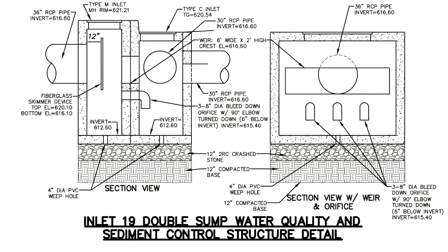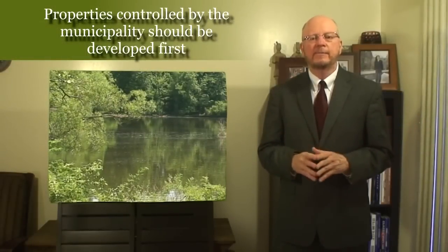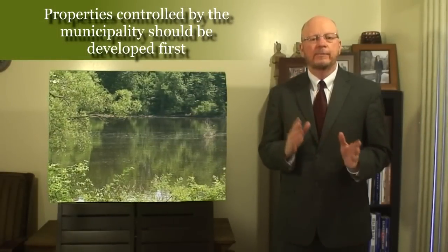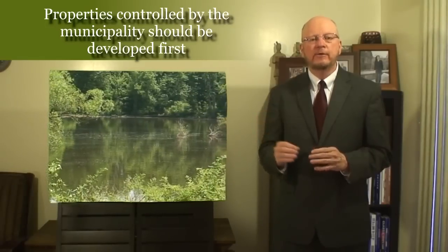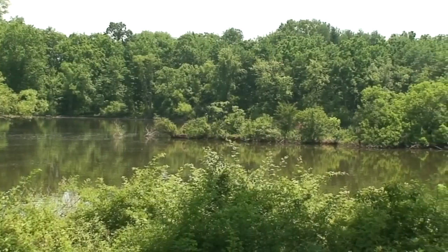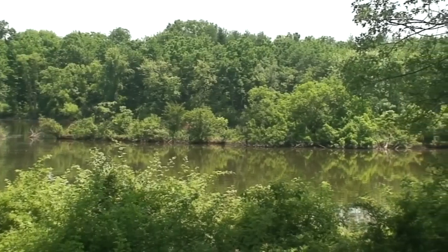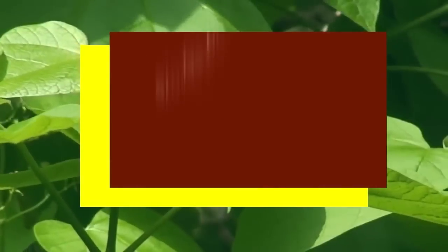Some property owners may just allow a small structural water quality outlet structure, and that is better than nothing. Of course, all the areas controlled by the municipality where permission is not required should be used to the maximum benefit. And constructing a large wet bottom stormwater pond surrounded by beautiful natural vegetation is an improvement to any community.